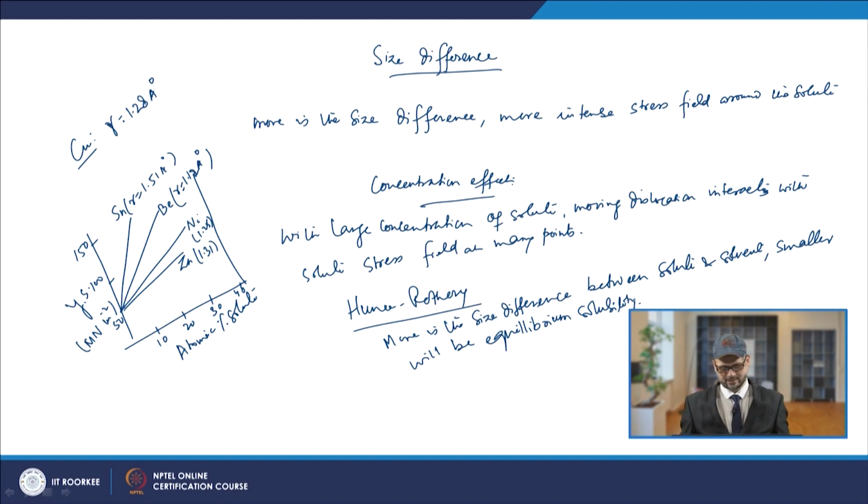And as we know, we get a very good engineering material in steel, because the normal solubility of carbon is about 0.02%, and it becomes 0.8% at the eutectoid temperature. So the solubility increases about 40 times when you increase the temperature, and then you cool it fast. An intense stress field is generated, which interacts with the stress field of dislocation movement.